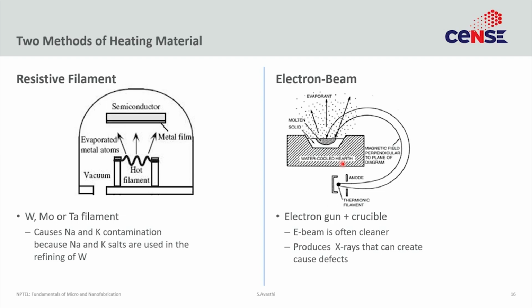So, that further assures that any impurity in the crucible would not go out, because the crucible is at an even lower temperature, so it has an even lower vapor pressure. The disadvantage of this technique, however, is electron beams hitting metals tend to cause X-rays, which can cause damage in sensitive devices.